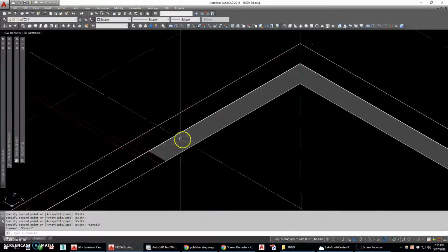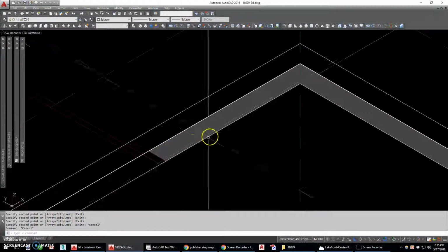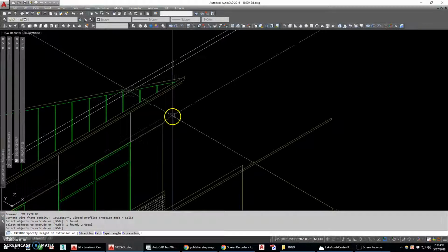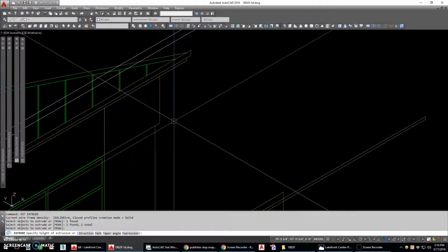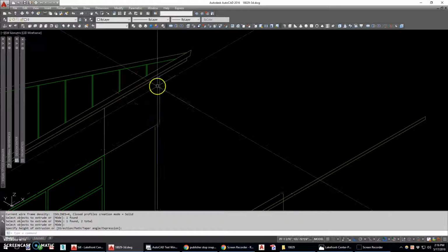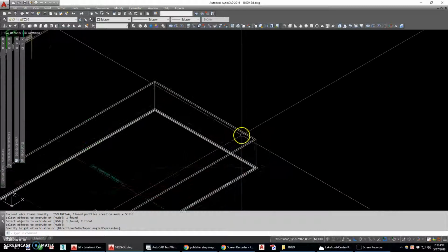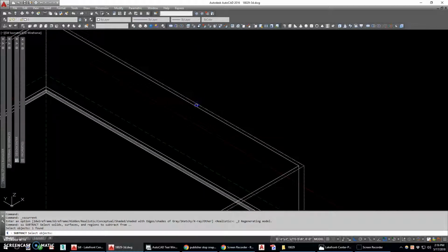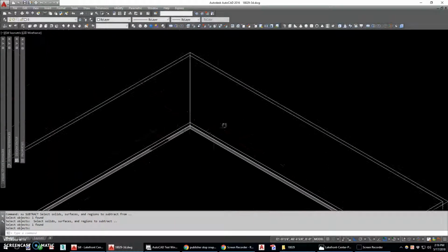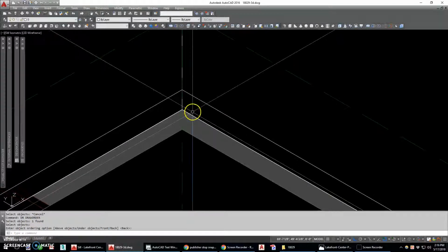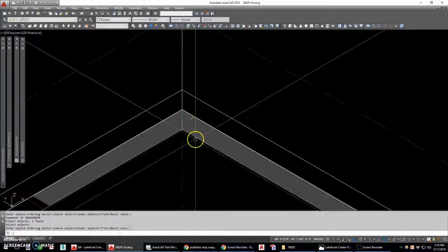Now what I'm going to do is create my main wall. So I'm going to extrude one of that inside line and one of these up to the height of, I'm going to go up to the roof. It looks like there's a bump out projection of some sort there. Right now I've got 2 lines. I've got to subtract the inner from the outer. I'm going to send this to the back and then send my reference to the back.